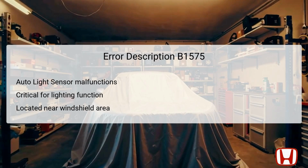The error associated with DTC B1575 points directly to the auto light sensor. This sensor is responsible for measuring the ambient light level and communicates this data to the vehicle's control units. If it malfunctions, the automatic lighting system may not respond correctly, leading to potential safety issues during nighttime or variable weather conditions. The sensor is located in a position that allows it to effectively gauge the surrounding light, typically near the top of the windshield in the driver's side area.